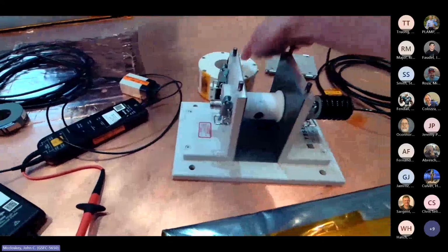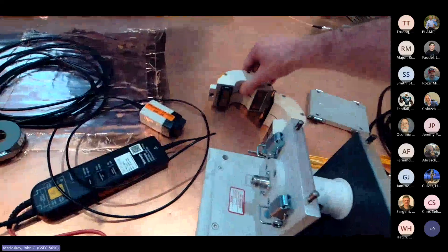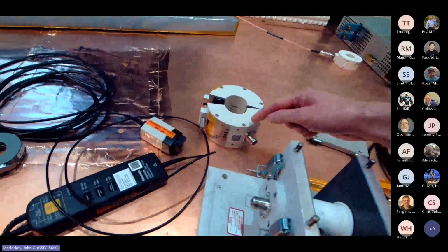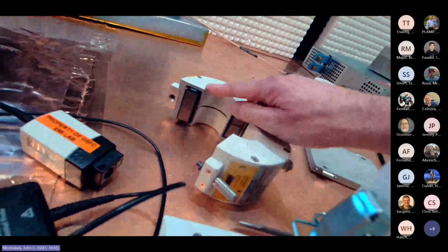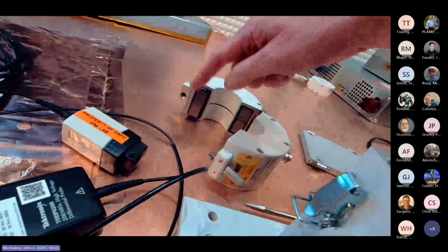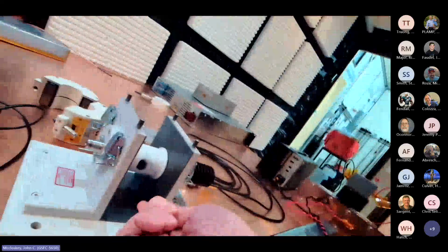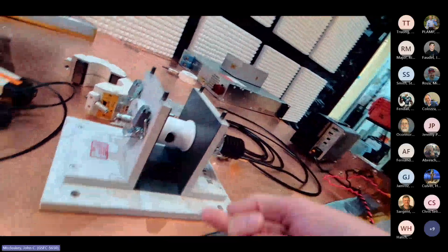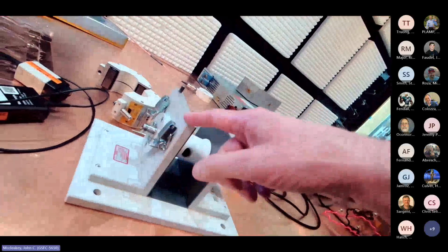So when you put the injection probe around it, it wraps around this thing. And when you apply your signal to the input connector of the probe, it ties to a coil of wire that wraps around the magnetic core. You can see the magnetic core here, and it induces a magnetic flux that is captured in that magnetic core. The magnetic flux couples through that loop and induces the potential in the fixture, and then we'll tie this to our scope and we'll measure it. But we'll get to that in a few minutes. I'm going to show you a couple of things here first.